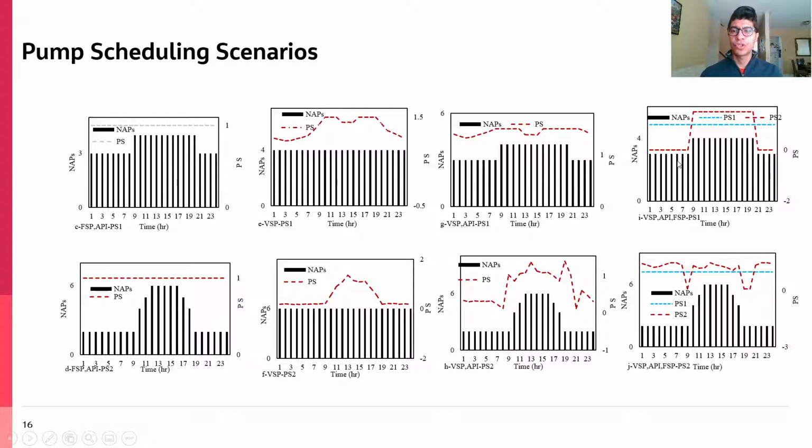So the top row shows pump station number 1, in which we have 4 pumps. The bottom row shows pump station number 2 in that hypothetical sample system, which has 6 pumps in it. In the first mode or scenario of pumping that I'm not showing here because it's not very exciting, but we're going to have it as a part of our comparisons, is our baseline scenario. Leave all the pumps on, and I am totally aware that it's not a very practical scenario, but just for the sake of comparison, I'm mentioning it. In terms of comparing the costs, the power consumed, how the leakage is improved, how the performance of the system is improved, we're going to compare all these 4 other pumping scenarios to that baseline scenario that assumes all of the pumps in both pump stations are on.